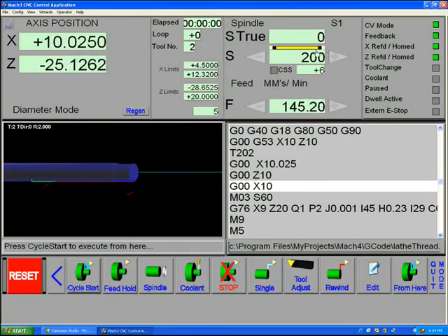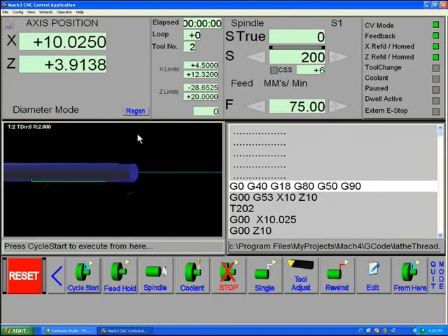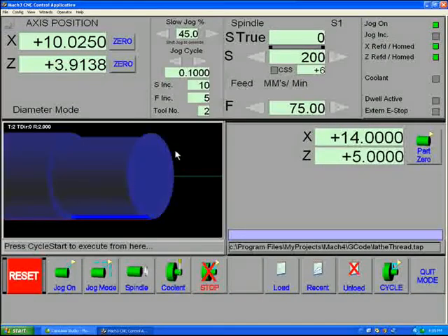You'll notice in this case I have the spindle on, but I have no spindle true RPM reading. That's because I don't have the machine hooked up at the moment, and I'm not feeding a spindle pulse into the machine. I'm going to stop this. Tools are selected in Mach 3 with MDI lines or by typing into a tool selector. Normally, however, you will select them with an MDI line or in G-code, of course. T01 would mean tool 1, and the following two numbers would mean offset number 1.